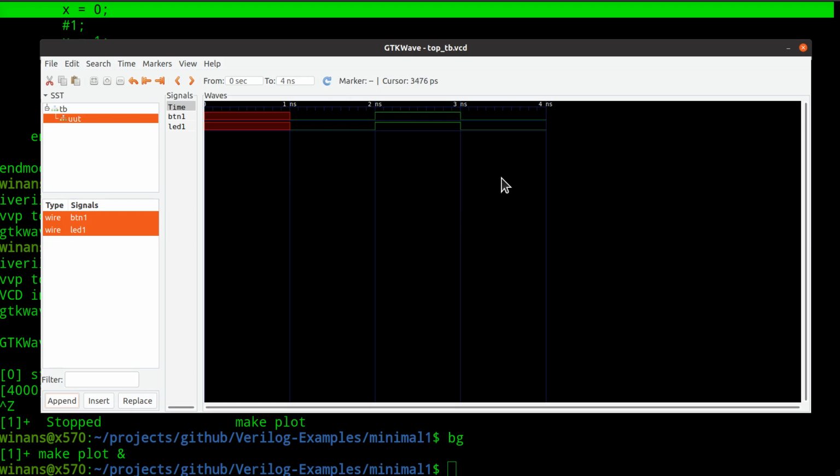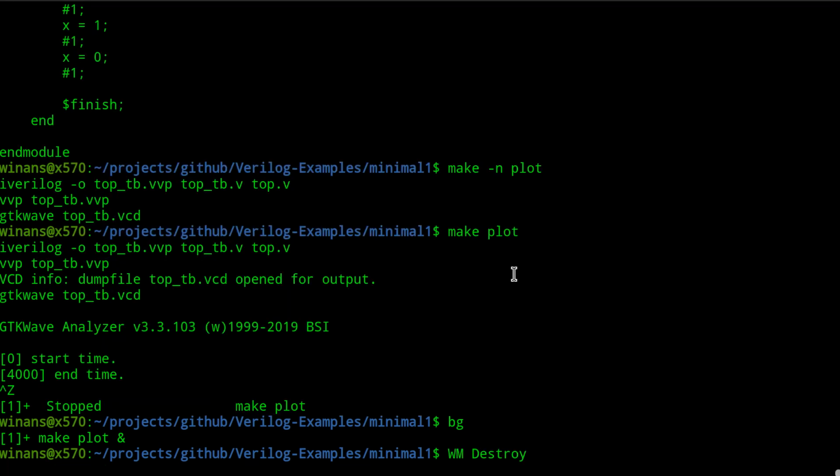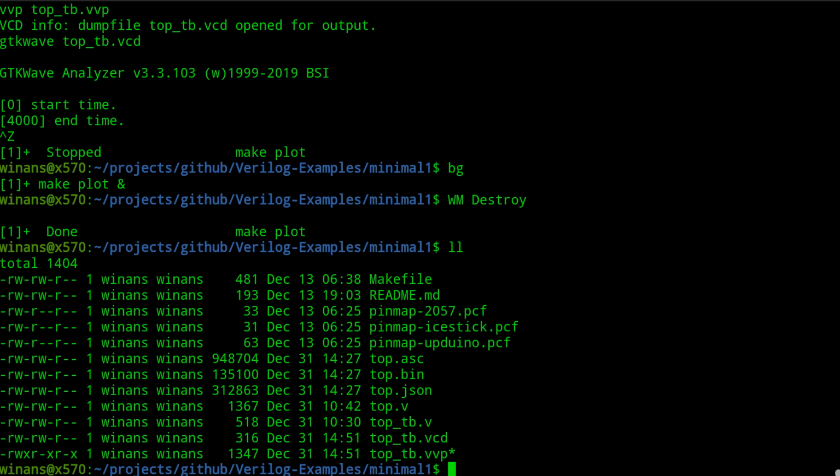You have to simulate what the FPGA would do and plot it and look at it on here to make sure it's okay. All right? So once you get over the initial excitement of, hey, I have an FPGA and lights can go on and off, when you need to program it for real, you're going to spend a lot of time creating these test benches and plotting your results. So that is where we're heading in the first round of application programs that we're really going to play with. All right? Because, I mean, this is everything. You've got to simulate these things.